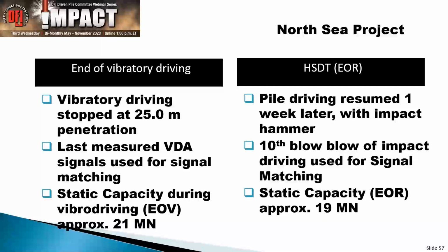So our experience on granular soils is much stronger, but we can fairly accurately come up with a capacity prediction of the pile. It remains an estimate, because even with signal matching, when you talk about high-strain dynamic testing, it always remains an estimate. It's not the final value, because signal matching doesn't have a unique solution, and therefore it is subject to what the analysts think.